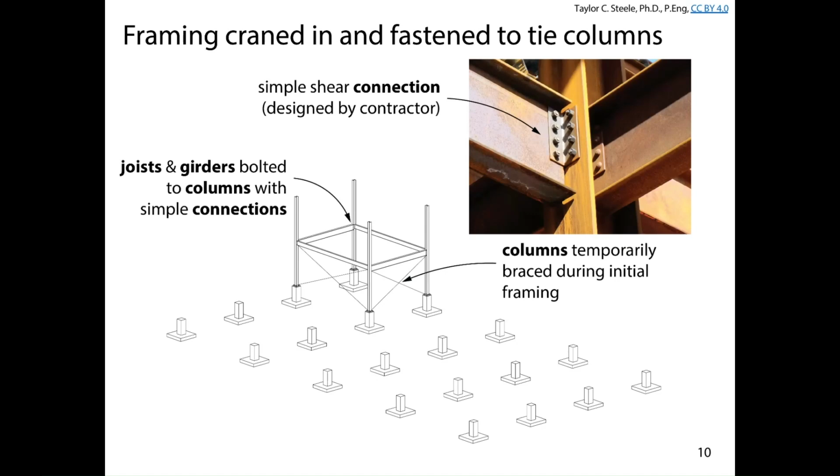Basically, what that means is it's designed to resist the shear force that's at the end of that beam. And what it also means is it allows us to treat all of our beams as if they're simply supported, for the most part, as long as they're using these types of connections.